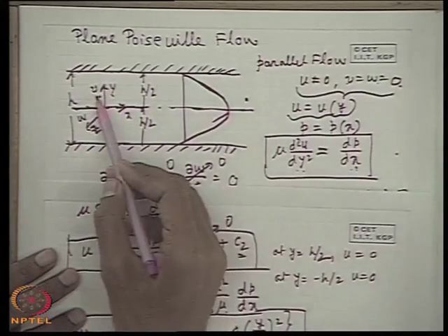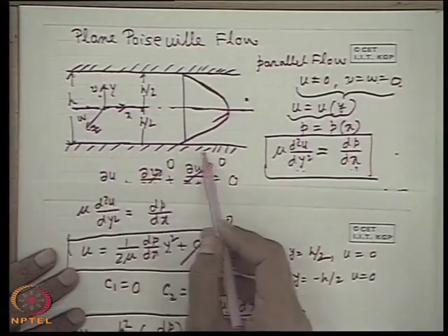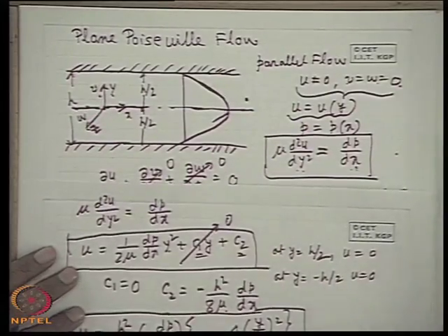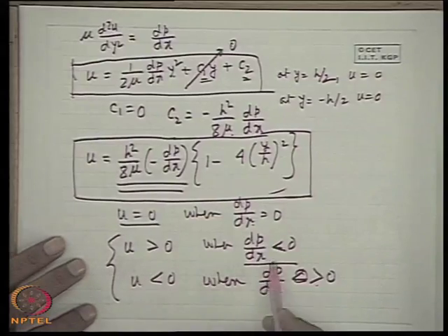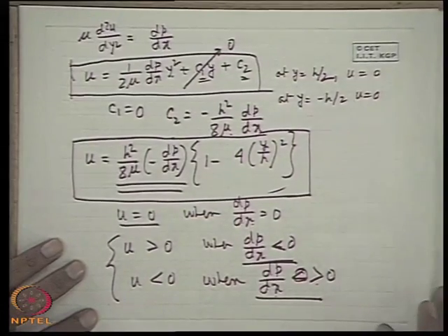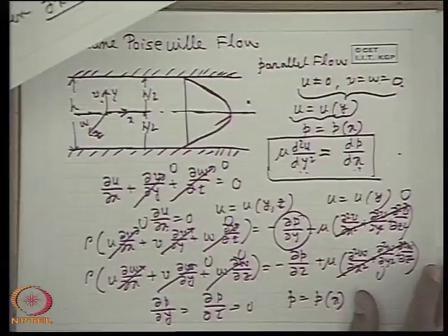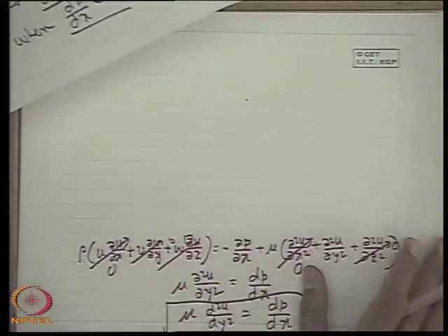So, therefore, flow will take place in the direction of favorable pressure force, that means in the opposite direction, that is, the flow velocity is negative. So, flow velocity takes place depending upon the direction of the pressure gradient. Pressure gradient is the sole cause of the flow in this case. Now, we go for the routine calculations of shear stresses and flow rate.